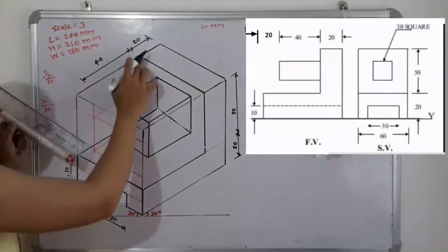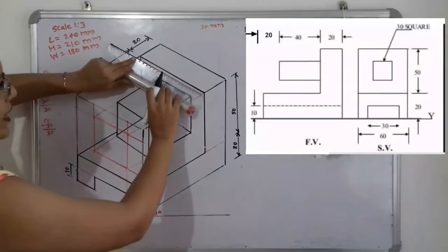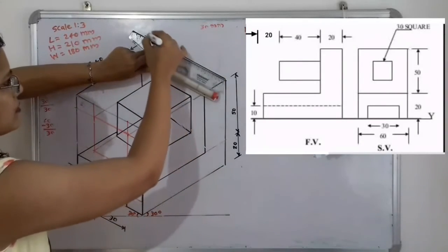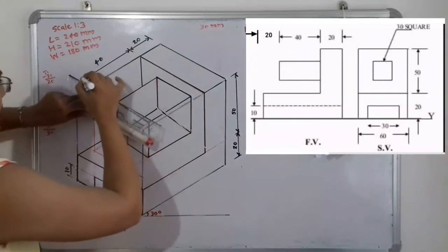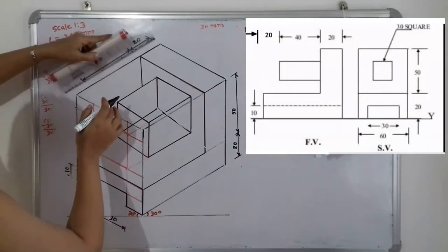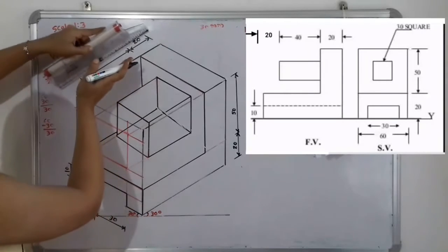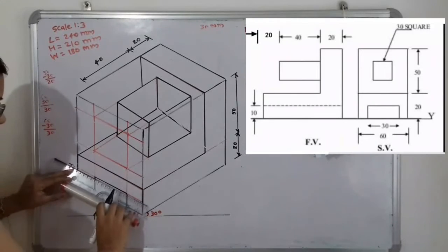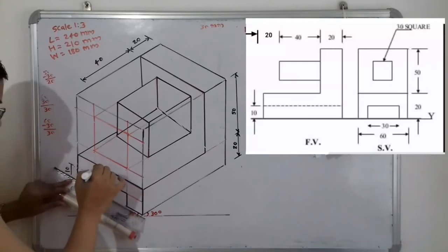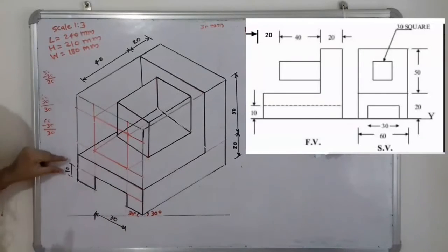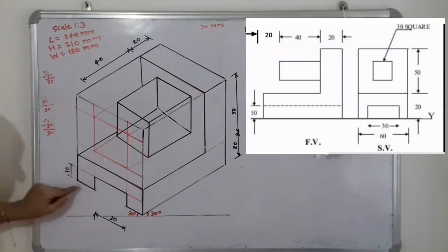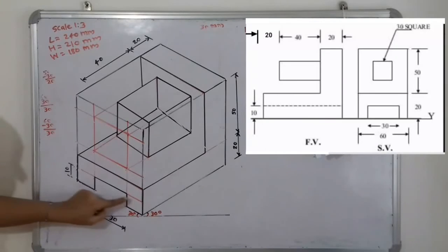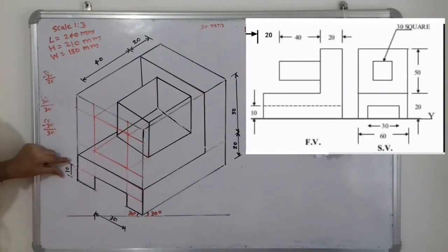In the same way, now here is the width line. So here we have to take the lines in the direction of this. So here we have to mark the lines, and here we have to show the dimension in the direction or parallel. These lines should be parallel to each other. So for height you can draw the straight vertical line, but it is along the width. So here for the mark we have to use the distance. That is, what is the distance here? That is in between these two lines. So this line is inclined at 30 degrees. So here we have to draw the line inclined at 30 degrees, and this line is also inclined at 30 degrees. So this is the length. That is, this is the dimension that we have to show.